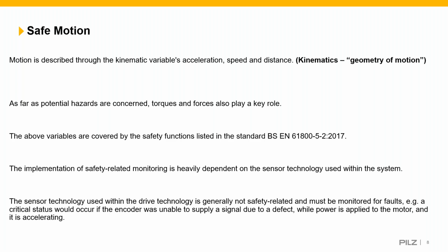The implementation of safety-related monitoring is heavily dependent on the sensor technology as well, so we'll look at that. The sensor technology used within the drive technology is generally not safety-related and must be monitored for faults. So, for example, a critical status would occur if the encoder was unable to supply a signal due to a defect. While power is applied to the motor and it's accelerating, this obviously would cause quite an issue.